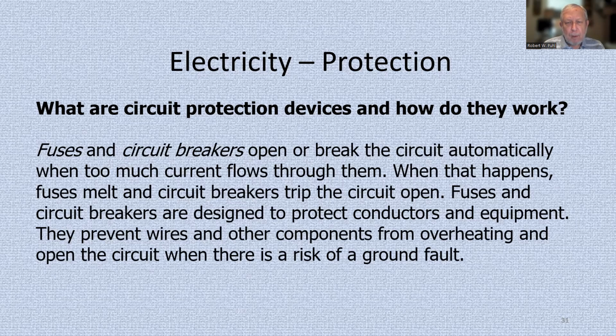Fuses and circuit breakers open or break the circuit automatically when too much current flows through them. When that happens, fuses melt and circuit breakers trip the circuit open. Fuses and circuit breakers are designed to protect conductors and equipment. They prevent wires and other components from overheating and open the circuit when there is a risk of a ground